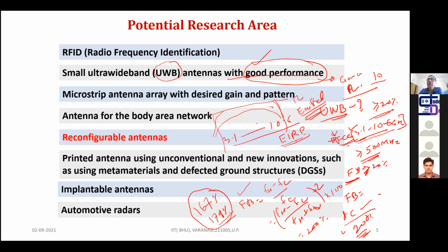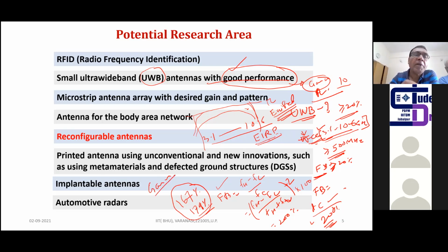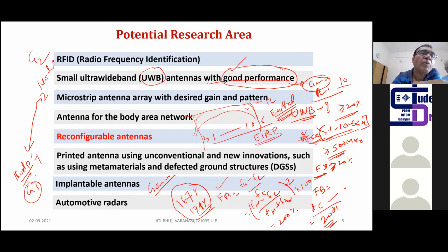Further, only calculating or measuring the gain of the antenna is not sufficient. For particular applications, right now everybody is working on sensor networks. Suppose node 1 is there and another node is somewhere else, and we would like to transmit the signal from node 1 to node 2. Antenna 1 gain is G1 and the node 2 antenna gain is G2. Whatever G1 we have has to be communicated properly with G2. So how can that be possible? Then you have to think about the link design.